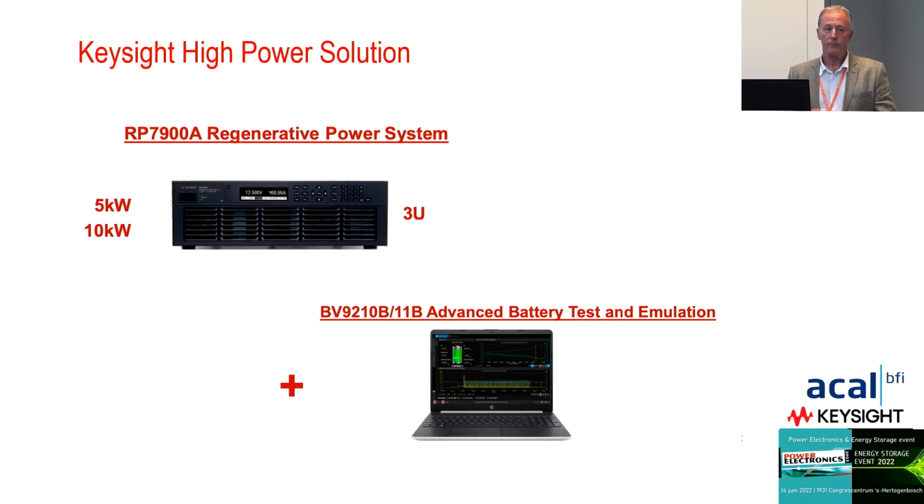And I would imagine that you would put in a lot more safety, because for example, if you're developing a new BMS, my prototype 1 probably is not sitting in a battery. Yes, and that's one of the reasons why you need an emulator, right? So there is inherently a lot of safety features. Obviously it's inherently safer to use something self-contained with shut-off control and current limit, rather than a live cell, where, as you say, you can get thermal runaway effects, which would be quite dramatic for something like a 100 kilowatt solution. Thank you, good question. Anything else?